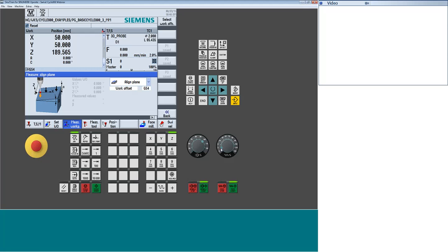So the way this works is I would just move a probe down to some point on my part. So I'm going to bring her on down. We'll bring it just down in the negative a little bit. Of course, we haven't set any zeros or anything. So come down, maybe right now I was just about ready to touch. Now with an automatic probe, all I have to do is hit cycle start. The system will feed down, touch the edge, and then save that recorded location. I saved that value, and I see that by it giving me the P1 in blue.